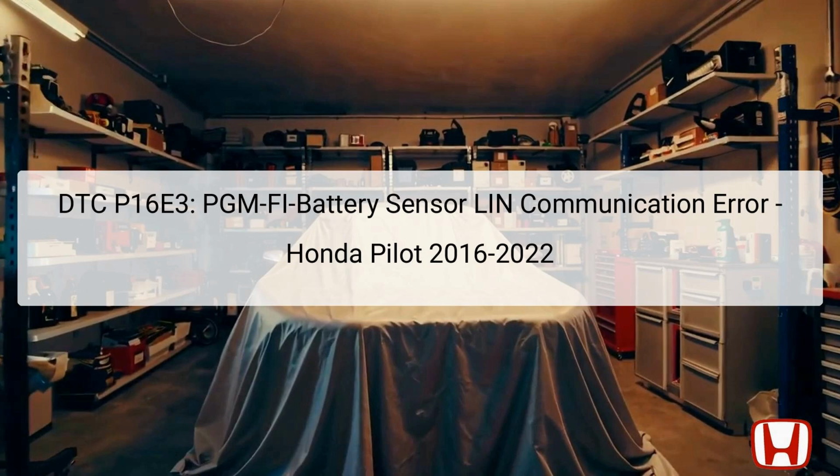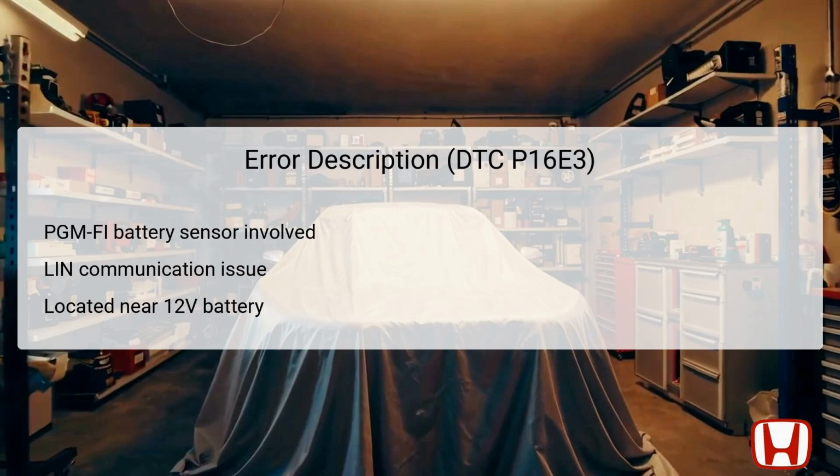The battery sensor is critical as it monitors the voltage and health of the vehicle's 12-volt battery, helping the engine control module to optimize performance and efficiency. In this presentation, we will explore the components involved, causes of the error, symptoms, and step-by-step troubleshooting methods to effectively resolve the issue. The P16E3 is a diagnostic trouble code, DTC, indicating a communication error within the PGM-FI or powertrain control module concerning the battery sensor.